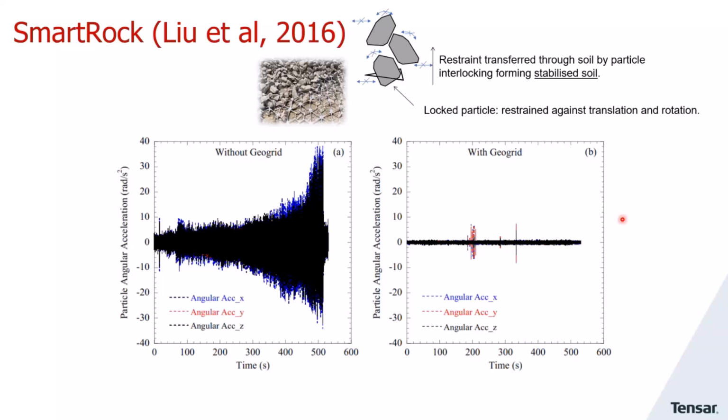It is not the same as chemical stabilization, where we bind stones together, comparable to cement, but we mechanically confine unbound granular particles in the apertures of our geogrids, and in turn these confined stones interlock with the above-lying stones, making a very stiff layer resistant to deformation.